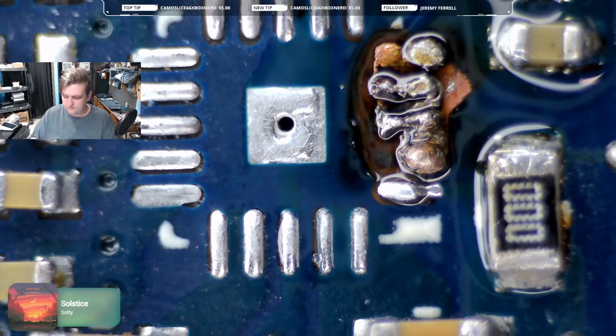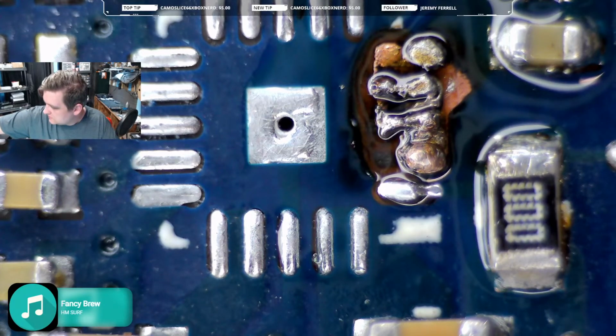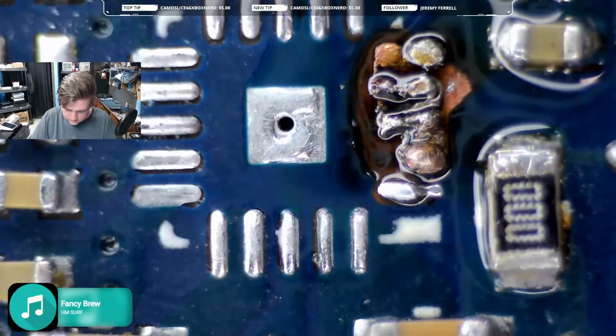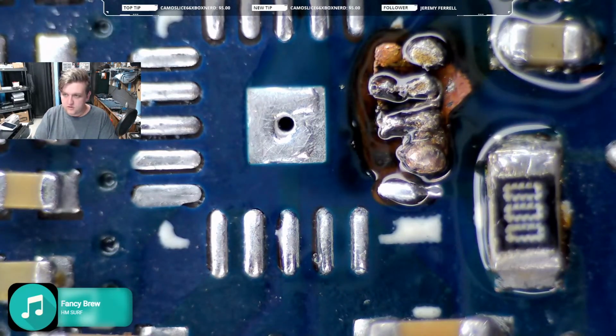I'm going to change tips. I think I need a slightly larger surface area. Not by much though. Let's see what this guy looks like. That's a little too big. How's this one? D08. That'll work, I think. Just don't wanna take too much of a chance of hitting that resistor right next to it. I can knock that guy off, and the cap right above the resistor too.